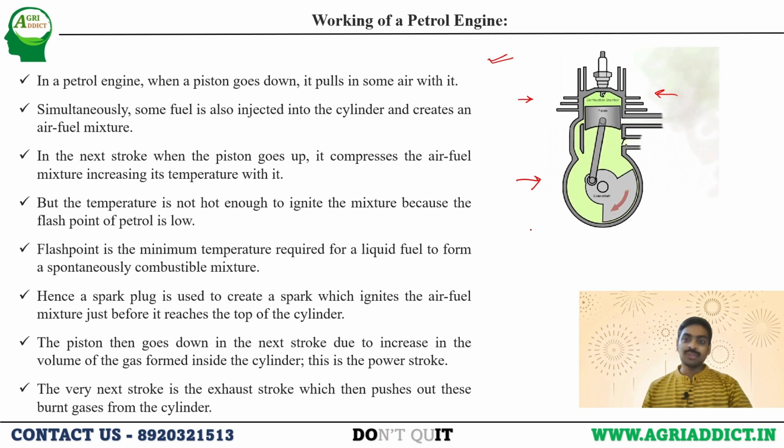This is in brief what I have explained, how the petrol engine works. The inlet valve opens, the fuel and air enter, and later the inlet valve gets closed, and burning of that particular fuel with the help of the spark plug takes place, because the compression pressure created by the piston is not sufficient to ignite the fuel. So the spark plug is taken help of here.